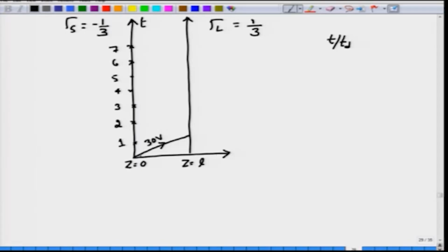So, that is the reason why we have drawn a straight line here. If there was some kind of nonlinear length to delay relationship, then this could have been a different curve, but luckily as you increase the distance, the propagation time will be L by U, U is constant and L is the one that is linearly changing, and therefore the delay changes linearly.